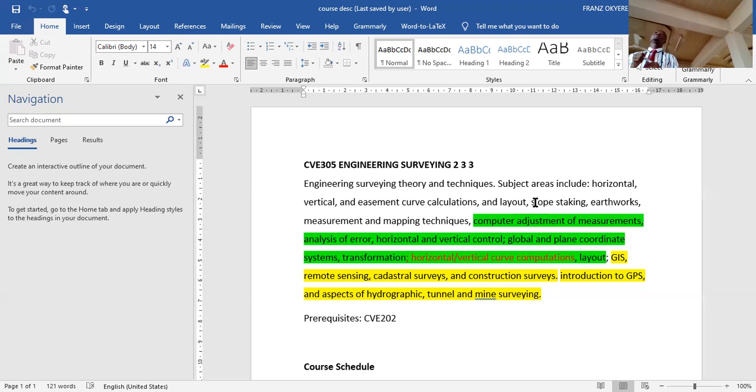We're talking about earthworks, volumes. Like end areas, calculation of volume using the end areas method. There are different methods of calculating area and volume. We have the Simpson's rule, we have all sorts of ways of doing it, the trapezoidal rule. So these are formulas. We take our time. If I come to class and we're in a hurry, put the formula down, take our time and see how it's done.